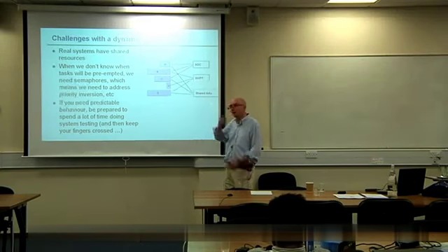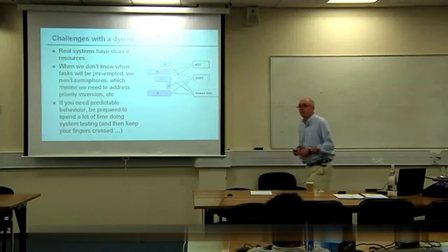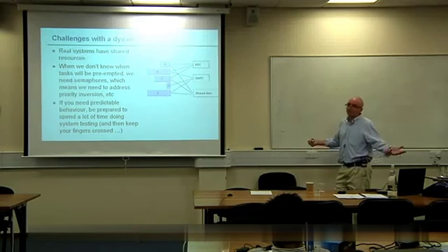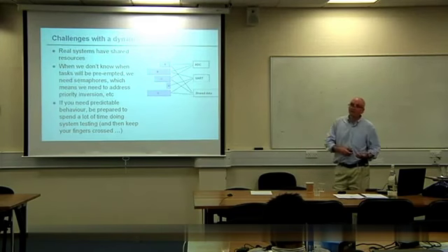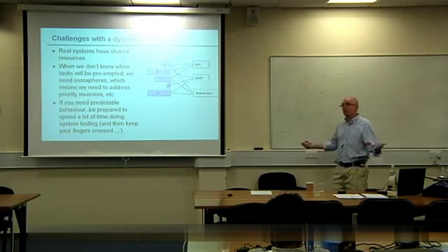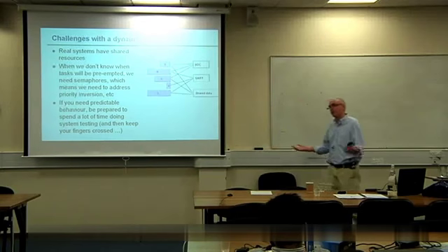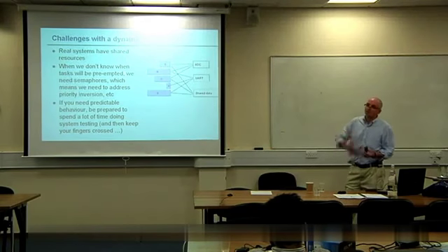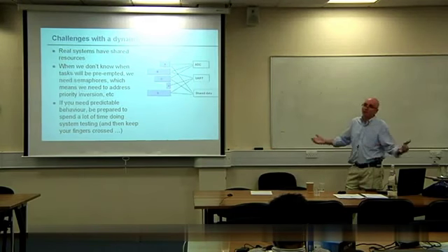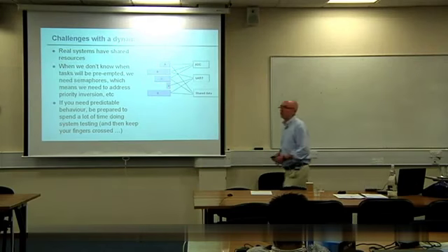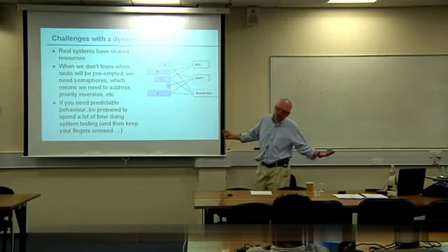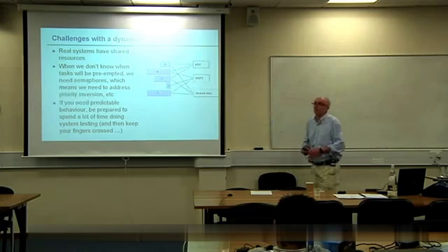So B cannot ask the scheduler what's happening next, because the scheduler doesn't know. That depends on the outside world, and you're back in the scenario where essentially the environment is in control of your system. Essentially, you've handed over control of your software to the interrupt system. And therefore, you've handed it over to the outside world, and you have no control over exactly what is going to be running when in the design.